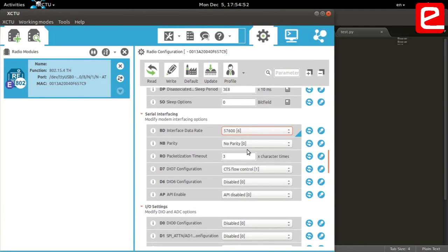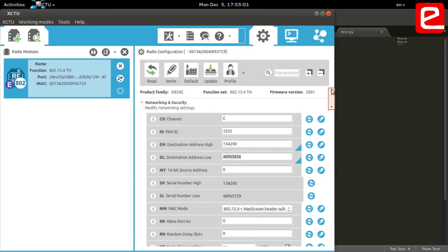You have to again wait for some time to do it. Okay, once it is done, similarly you have to configure the second zigbee module, and once both the modules are configured, you can use the serial terminal to check the module if you have multiple USB converters available with you. If you don't have it, you have to use some program on your microcontroller to test the module. For testing the zigbee communication, we will have another video to check the configuration.